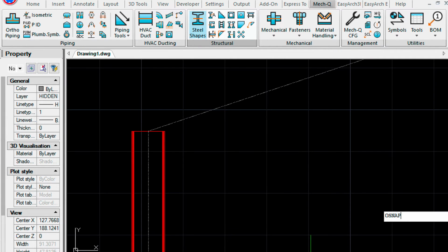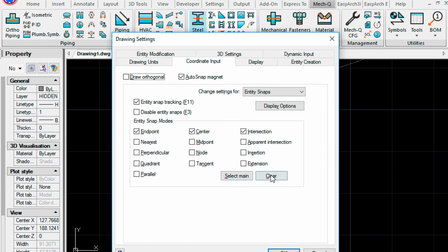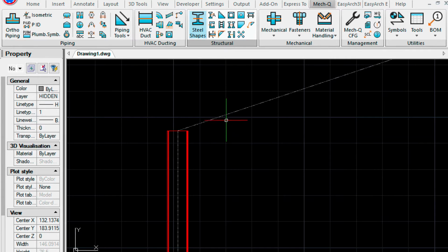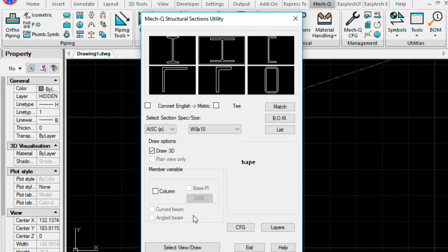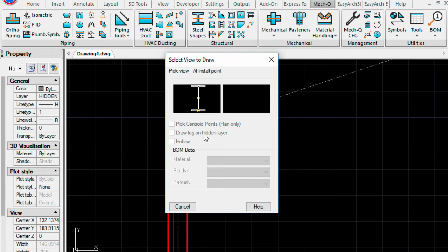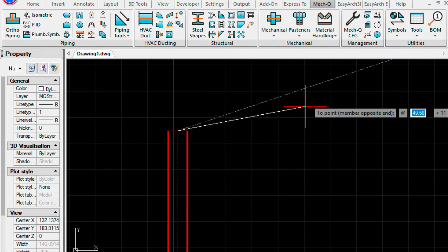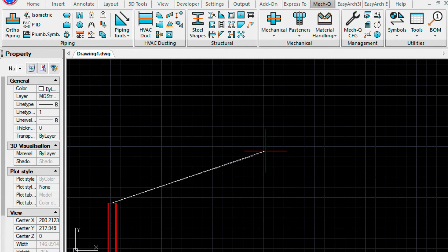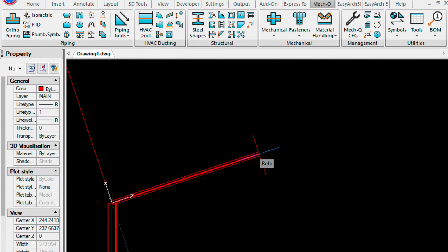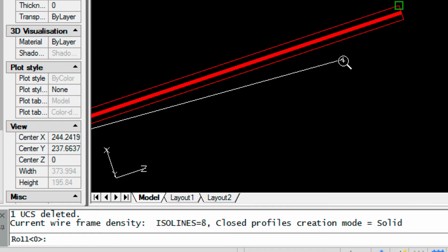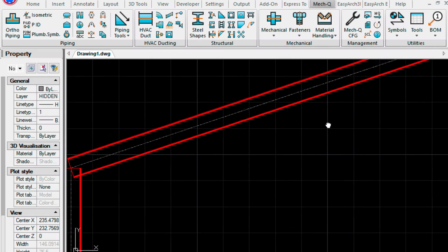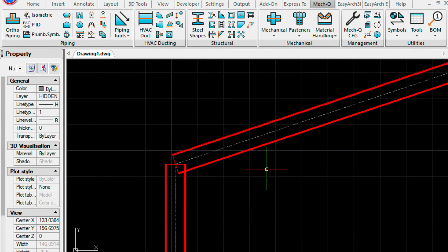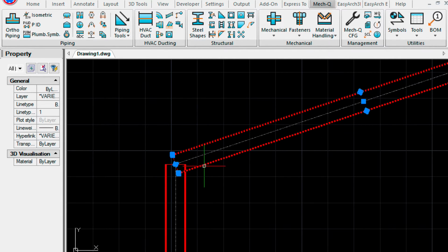Alright, and now we're going to check our OSnap settings, turn everything off, and just choose Endpoint for now. We're going to snap over our roof line, and it's just a matter of tracing that line using endpoints. We're going to rotate this as well 90 degrees so we get the beam pointing in the right direction. Let's move this down using direct distance down 6 inches.